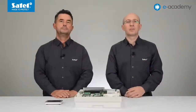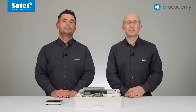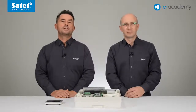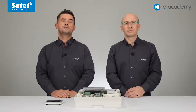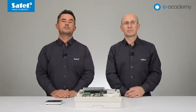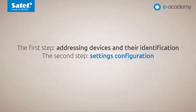Before we proceed to discuss the process of identification, let's clarify why it is so important to carry it out. As we mentioned in the last episode, the devices reaching the customer have the factory default settings. The control panel with factory settings supports all keypads connected to the bus regardless of what addresses are set in them. However, this mode does not allow you to program the system. You can only start programming after setting correct addresses for each device and after identifying devices connected both to the keypad bus and to the expander bus.